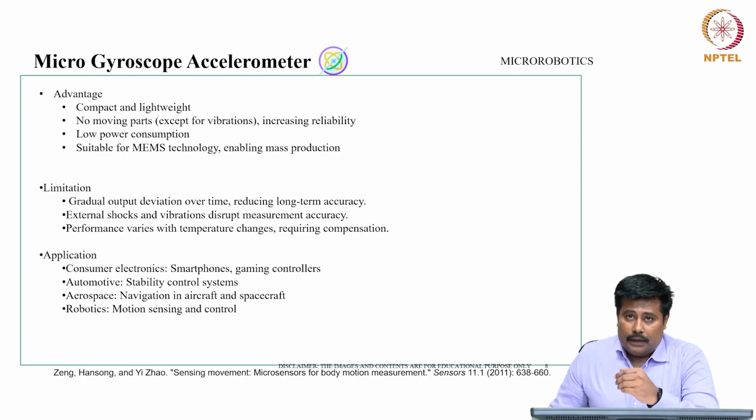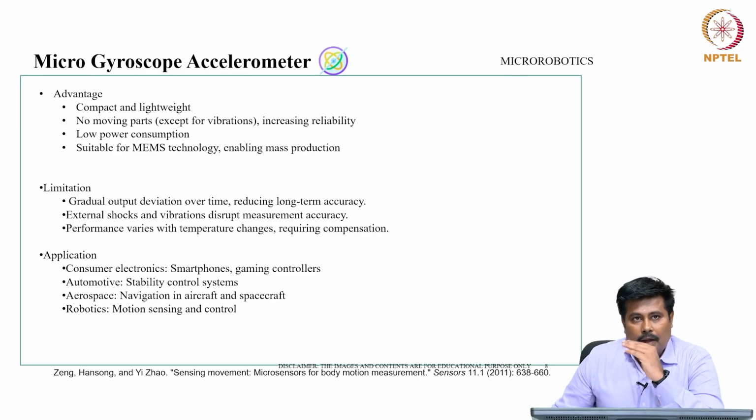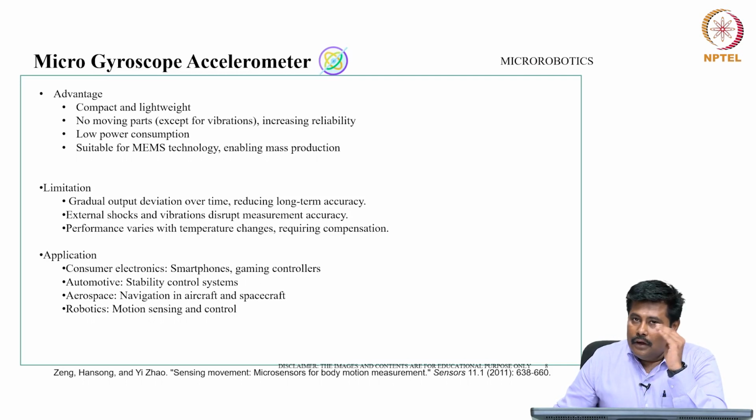The main advantages of such gyroscopes are that they are compact and lightweight, with no moving parts except for vibration, which increases reliability. The most important point is low power consumption, so it has potential usage in micro robotic applications. It is suitable for MEMS technology, enabling mass production.